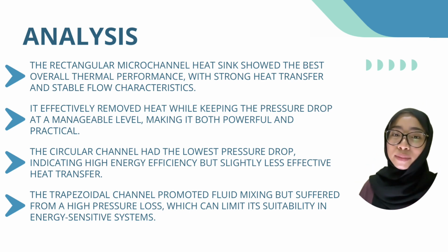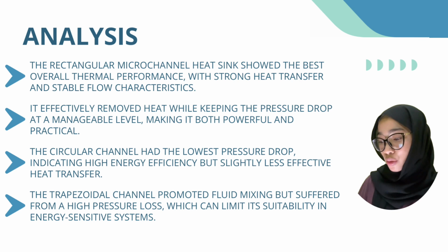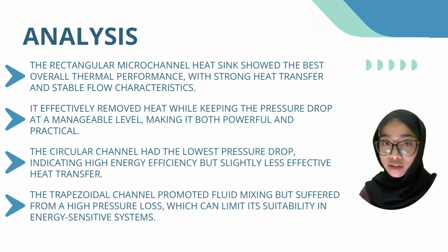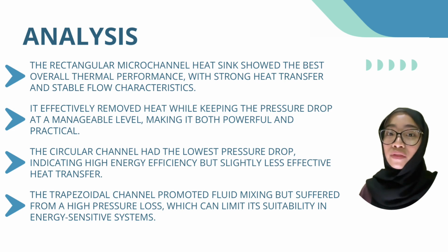And now I will explain our analysis and conclusion. I will begin with the analysis. From our simulation results, the rectangular microchannel gave the best performance overall. It removed heat efficiently and didn't require too much pressure to push the fluid through. That means it's both strong in cooling and efficient in energy use.